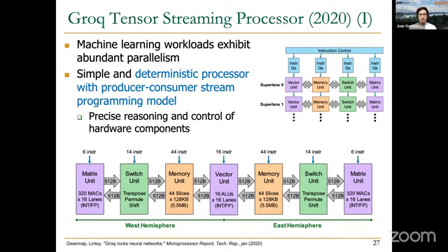If you think about the matrix multiplication, we are accessing rows, we are accessing columns of matrices. So the computation and the accesses to memory and the operations that we need to perform at any given point are quite predictable. That's why Groq designed a deterministic processor where they can orchestrate the flow of data over all the different units that the Groq system integrates. And here you can see already a pictorial representation of these units with matrix units, similar to the systolic arrays that we have mentioned earlier, switch units that are used for communication, shuffling data from the matrix unit to the memory unit. There are also vector units similar to the matrix unit, but intended to operate on a single vector, so they are more similar to a SIMD unit, and so on.